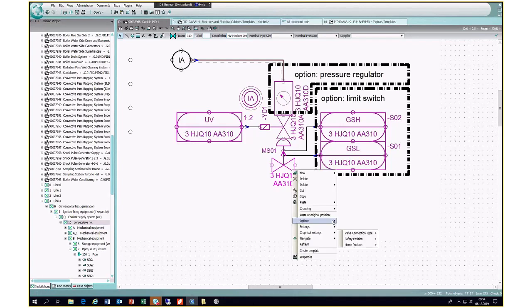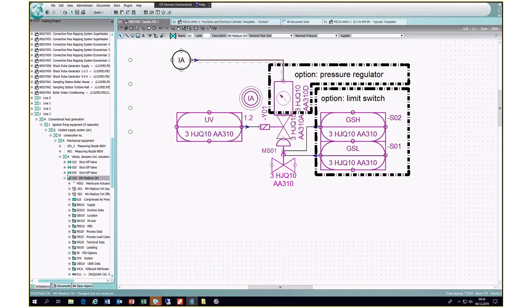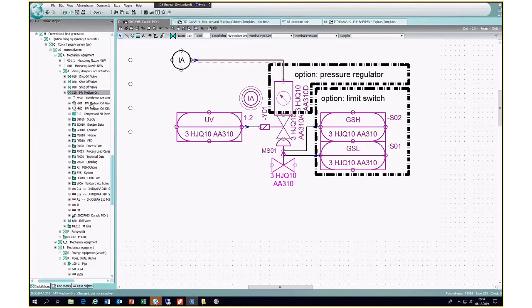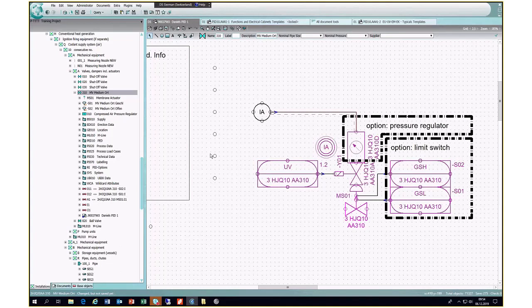And if I were to navigate to this object here, you see it here below. So the actual object here is this valve, and then you have a membrane actuator, and then you have 2 switches below it. Basically 2 end switches, I guess you can call those, right? And then you also have a few things, like this is the pilot valve, and this is like the regulator for the air, and this is the air supply.